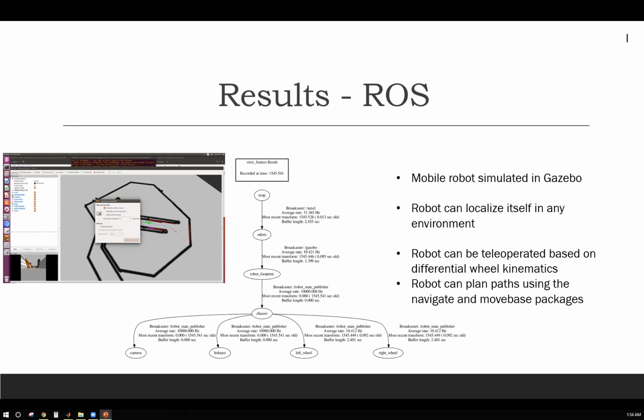Right now it's configured for about 50 particles, distributed around the robot, and the robot will attempt to determine its pose relative to the desired pose, in an iterative process to continue to reduce the error down to 0.